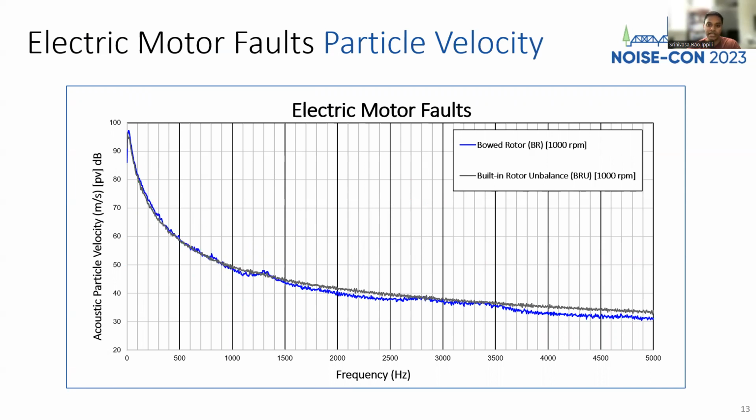These plots show that even for a vibroacoustic expert, it can be very challenging to establish discriminative features that can precisely distinguish different motor fault types. The traditional signal processing based features obtained from sound pressure level alone can either become incapable or insufficient, especially when a greater number of operating speed cases and background noises are introduced within the training data.